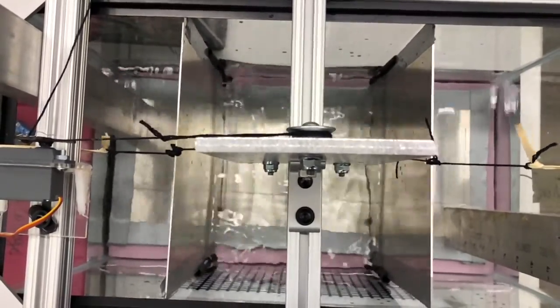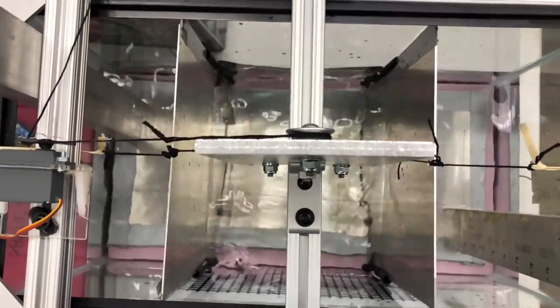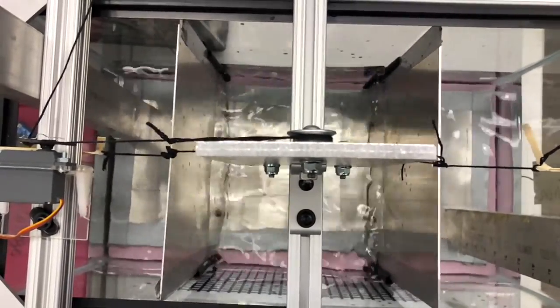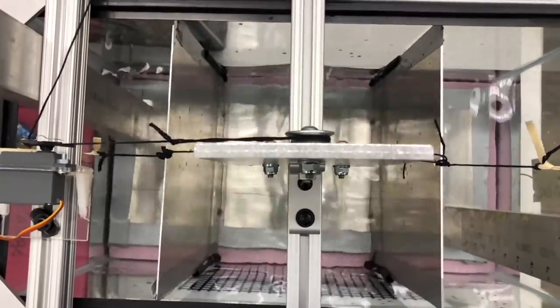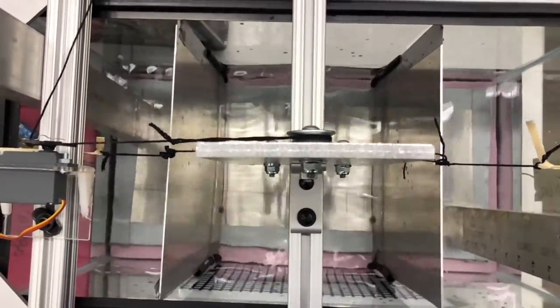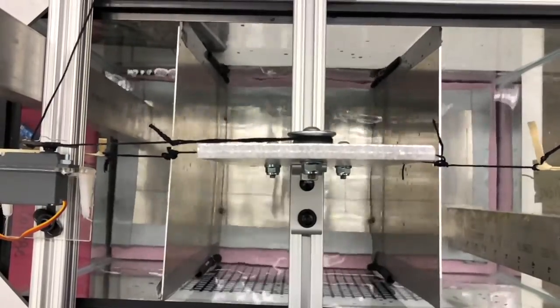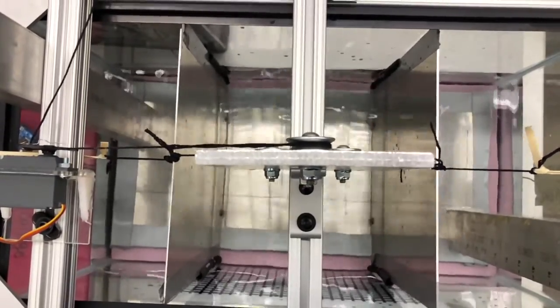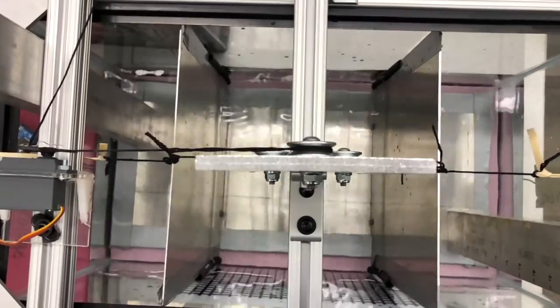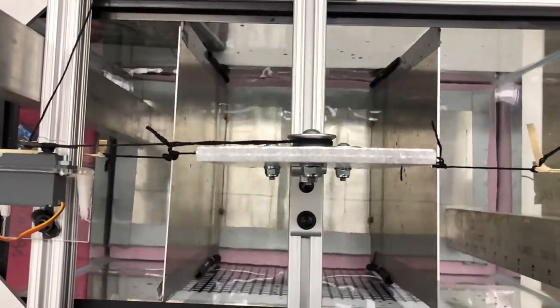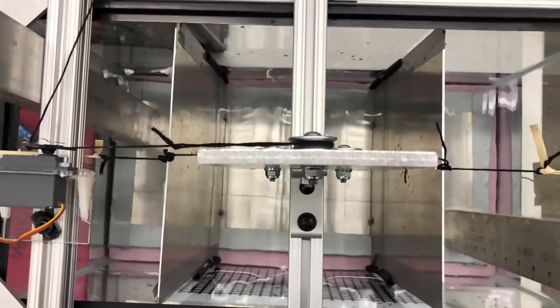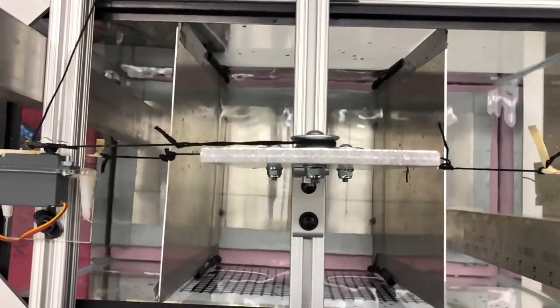Our apparatus fairly closely matches that of G.I. Taylor's, save for a few details. It consists of a fish tank with 2 aluminum paddles controlled by a servo via a pulley system. We used a standard 10-gallon tank and used rubber bands instead of springs to keep the strings taut and the paddles moving. We programmed the microcontroller to step up or down the frequency, holding at 15 cycles per frequency step. We ran the experiment either ascending or descending the frequencies to compare the results.